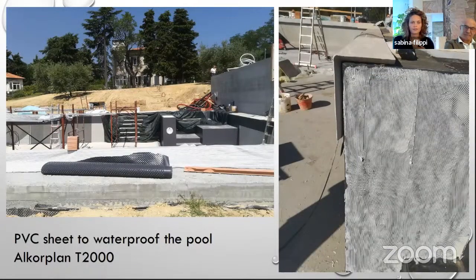Here we have the materials we used to waterproof the pool. We used this PVC sheet, premium quality, to cover it and make it waterproof. And we covered the edges of the pool with this sandstone, but to insert it, we used this putty that is resistant to salty water, because the purification system of the pool is made with salt water.